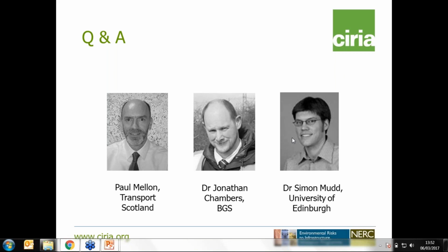Theoretically, yes. Where you have cavities opening up in the subsurface, you will get a contrast in electrical properties, which is what you need to image these things. It depends on depth below ground level. If you're deploying this technique using surface-based sensors, then you're going to be limited in how far down you can see. So we've used, for example, cross-hole imaging to look for deeper cavities where you need a deeper resolution. But in principle, yes, you could use this sort of technique for that type of process. And in fact, there are examples in the research literature where this has been done.